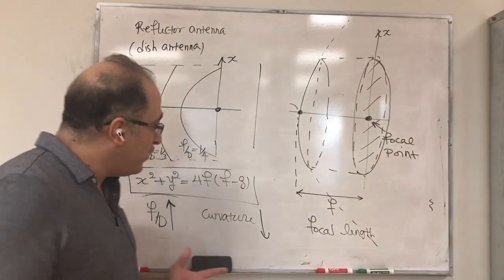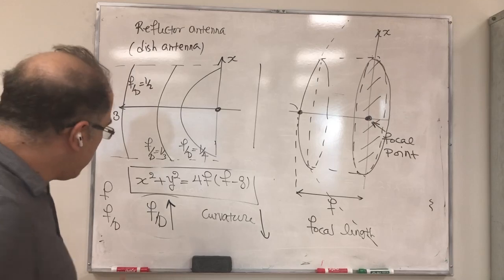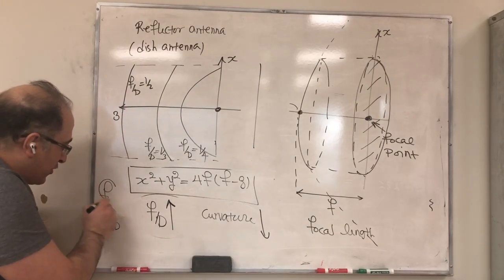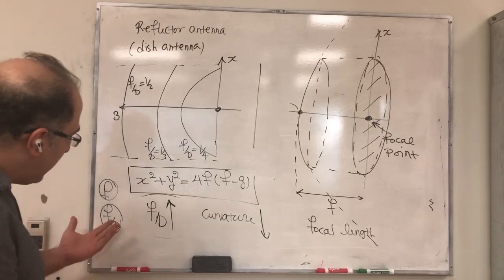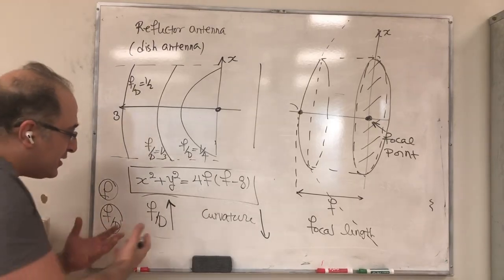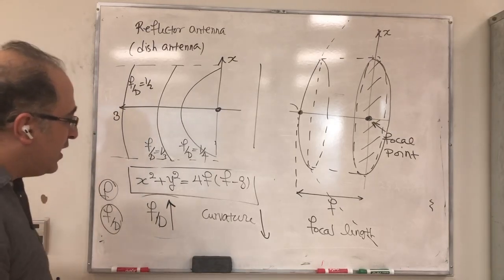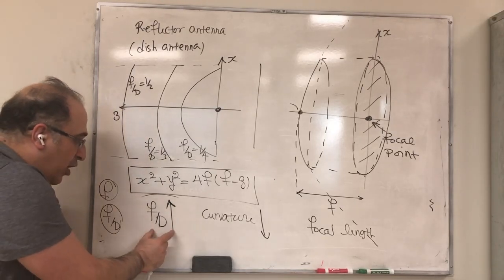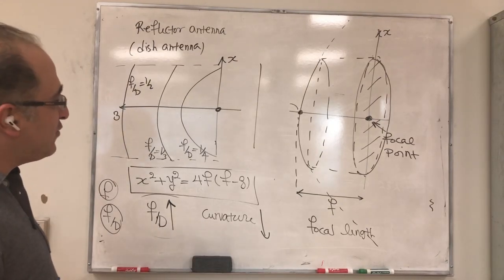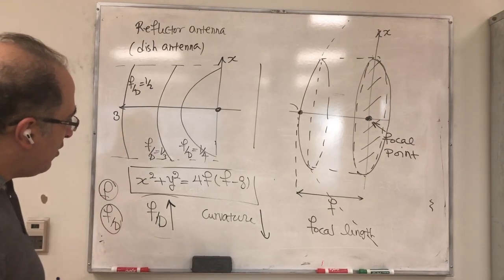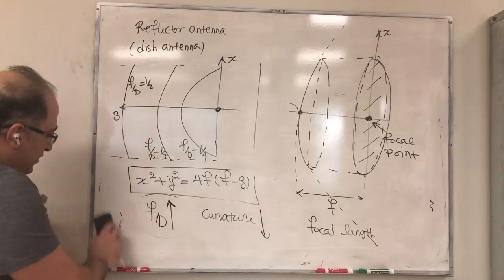So in summary, we mentioned that now we can represent our reflector antenna by a factor f, focal length, and focal length to diameter ratio. And the advantage of this representation is that you can understand the curvature of your reflector by noting that the larger f divided by d, the less curvature you're going to have. So let's elaborate a little more on the geometrical side of this.